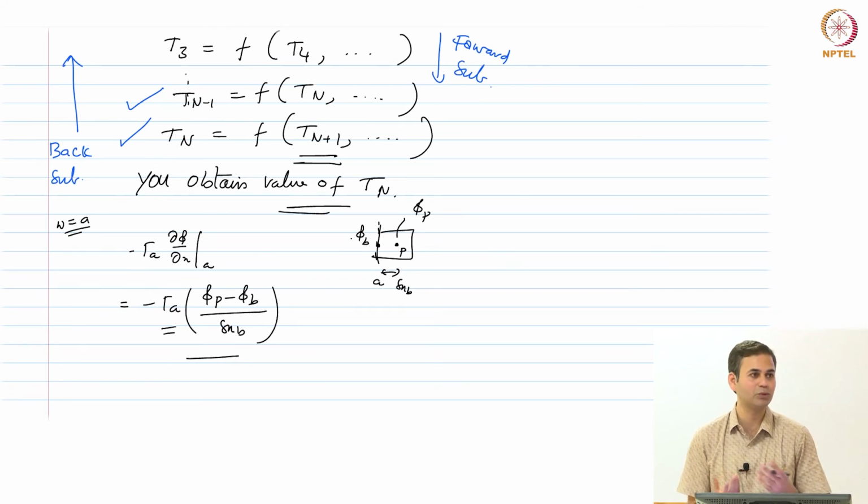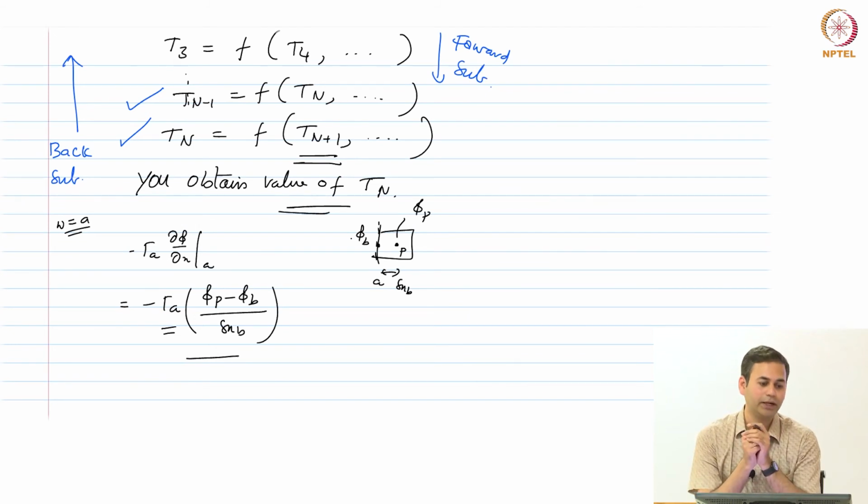That is basically the same as whatever interpolation you want to use. If you assume that you have the same material on the other side, then you can use gamma A as this thing. Now, how do I calculate gamma on a boundary face? Let us say I have an insulated boundary condition, I say Q is 0. Now, what will be gamma A? You do not need to calculate it, because Q is 0, so gamma partial T partial x would always turn out to be 0, that is all.